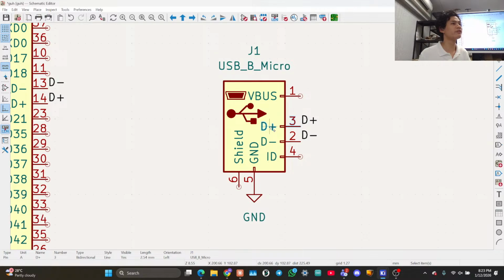If they're not labeled, then you stare at the pin number and you stare at the data sheet and you're like, yes, I wonder which pin is which. Usually you're fine. Usually it's labeled. If not, you can import the symbol from somewhere which you like. Usually the manufacturer will have the symbol. You can get it from them. Maybe I'll show you that later.